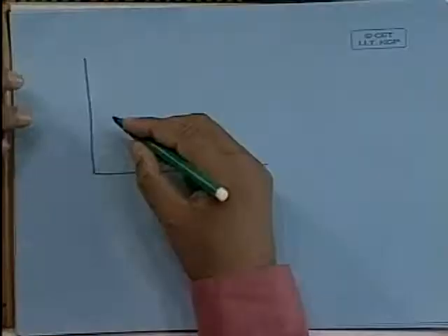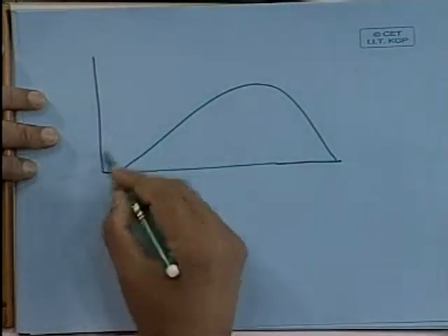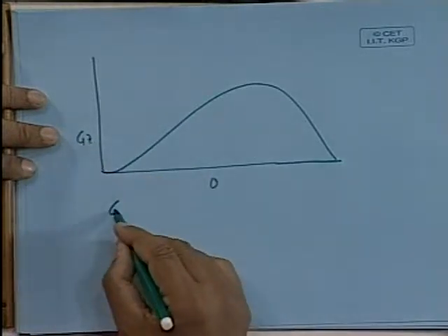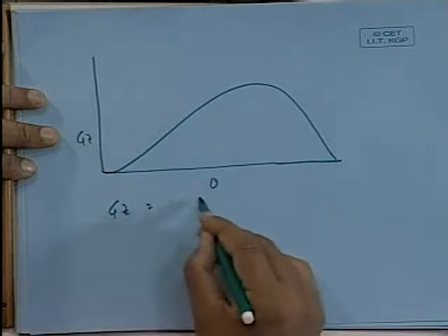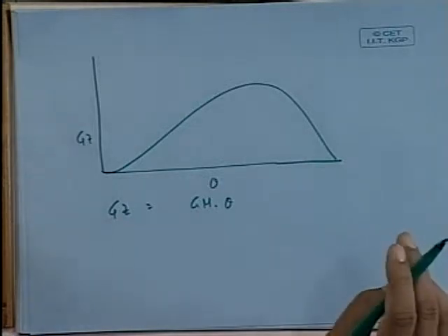And actually what would happen is that a ship which goes in different loading conditions with different KG, you have to ensure that this static stability curve has certain minimum basic properties. See, let us see how the static stability curve, I mean today we will discuss only less part. Say suppose, excuse me, static stability curve is something like this. First of all, this is GZ theta. First of all, we recall that GZ equal to GM into theta. Okay, when for small angle.